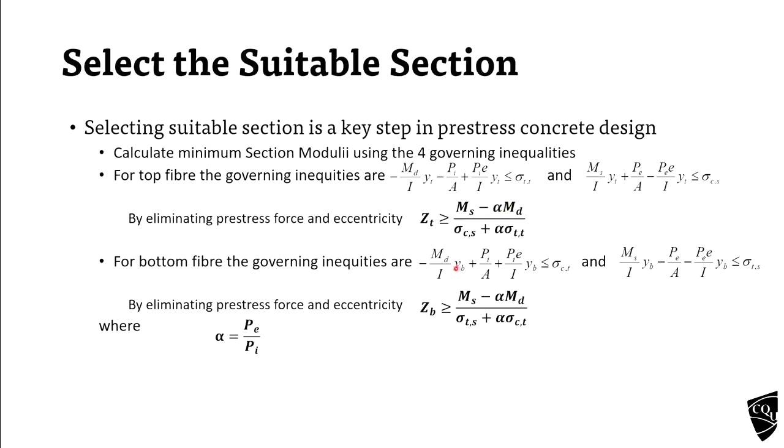Okay. Similarly, the section modulus for the bottom fiber should be larger than this one. So these two values do not contain the pre-stress force or eccentricity.